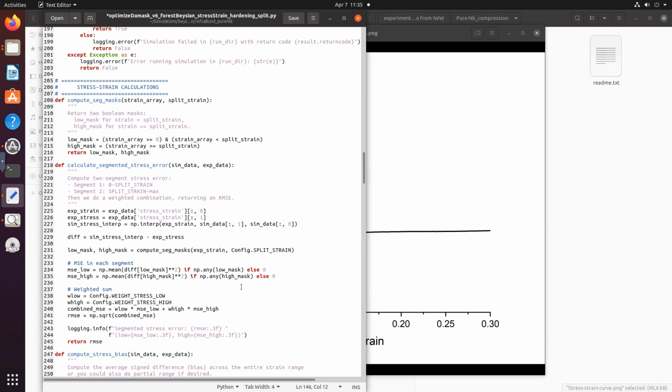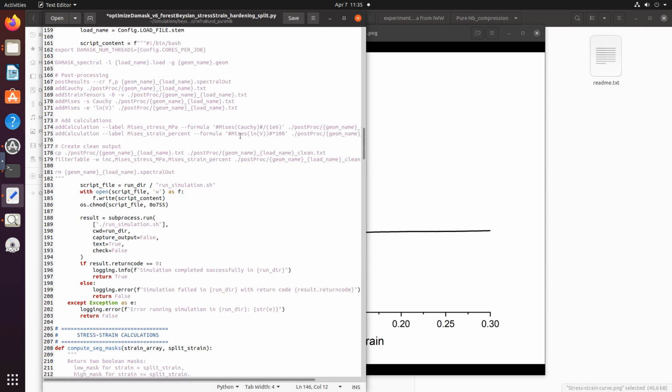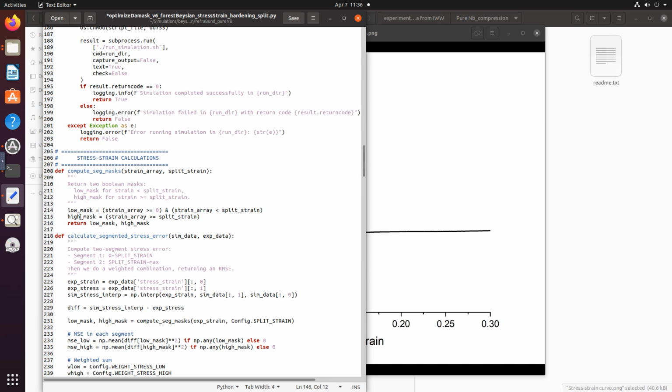And below this, what I just want to do is check the experimental strain data. My strain here is not in percentage, but the strain that I'm calculating here is. So either I do not convert this into percentage or I convert that into percentage. And of course if this is in megapascals, that should also be in megapascals. So my stress is the same. This is also in megapascals. And the stress in my material file was also in megapascal, so that is fine, but this is not fine. So either I remove this, or when I'm reading my data